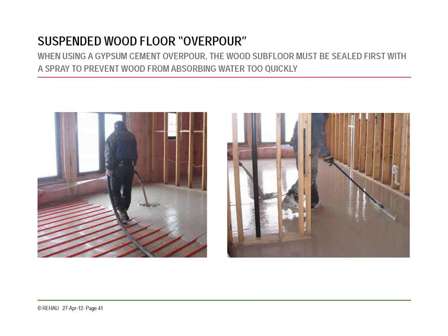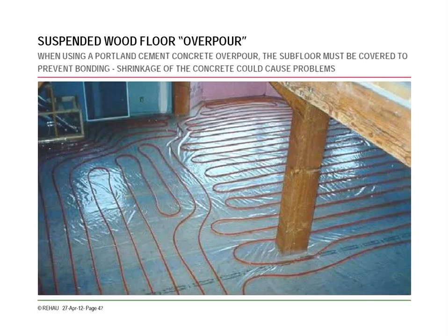Here's a couple installation pictures. One thing to note, for a gypsum cement overpour, the wood floor has to be sealed beforehand, and I believe it's, yeah, here we go, with a Portland cement overpour, the subfloor has to be covered to prevent bonding. So you just need to be cognizant of what medium you're using.